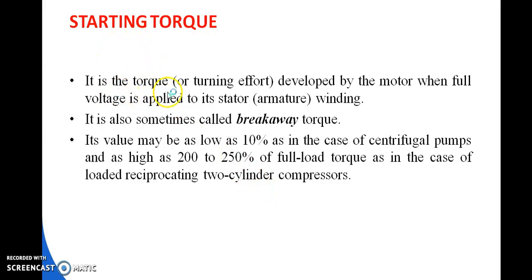It is the torque, or we can say the turning effort, due to which the motor turns. It is the torque developed by the motor when full voltage is applied to the stator or the armature winding. It is also sometimes called the breakaway torque.